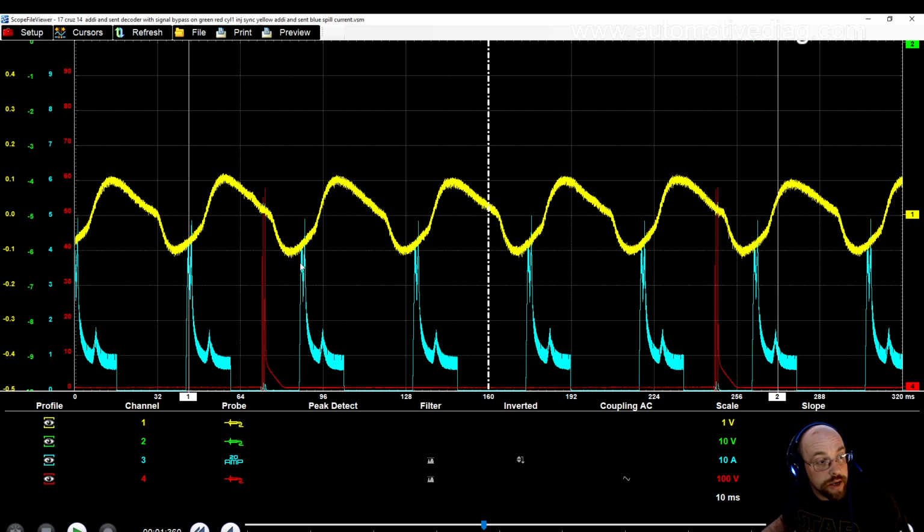So you can see here, here's our current flow starting on our spill solenoid to close it, and then our pressure increases to the apex of the cam lobe, and then of course our pressure starts to decline when the cam lobe backs away. So we can easily see here that we have a very even build on our fuel pressure every time our spill solenoid activates, which would be indicative of a normal fuel system.